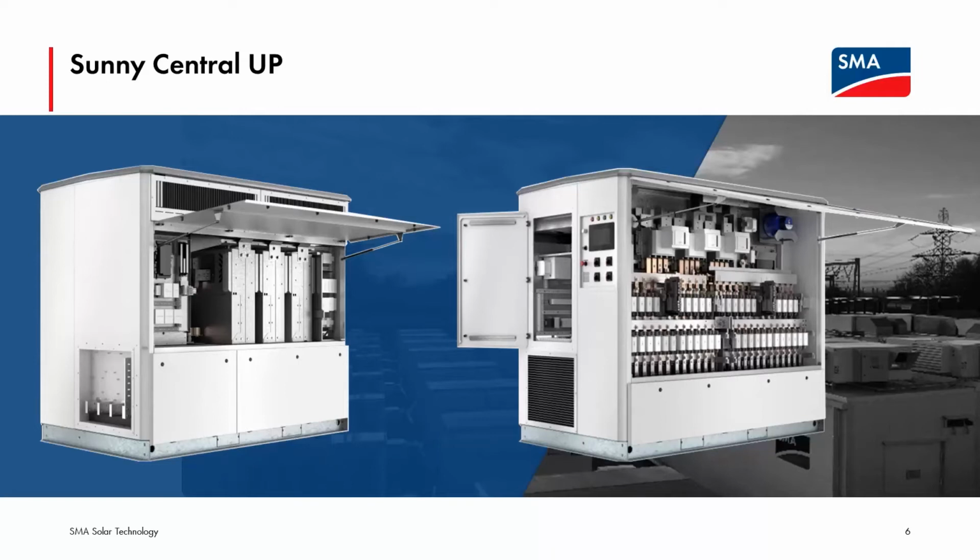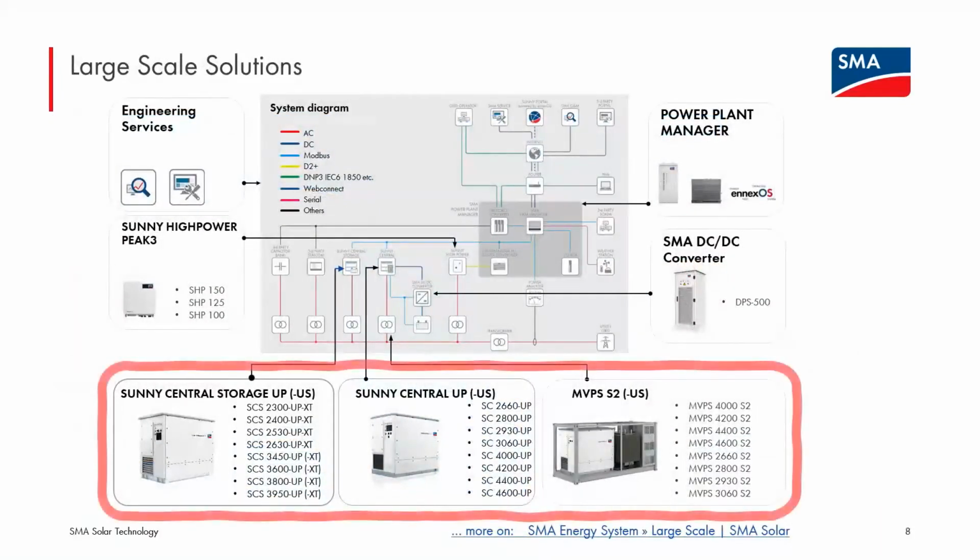On the front, we can see the AC connection terminals to connect the medium voltage transformer, stepping up from around 600 volts to 690 volts to whatever medium voltage is required for the project. Even within the group of a family member exist variants concerning the power rating or the DC input voltage range to perfectly match project-specific requirements. But all devices share the same electronic control boards and core of the control software. Here we can see the main types of Sunny Central storage and PV inverters in the SMA large-scale portfolio.